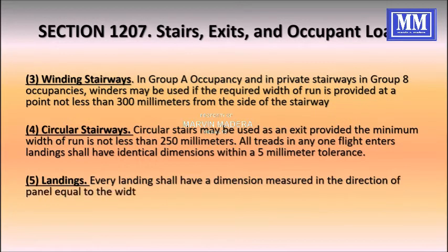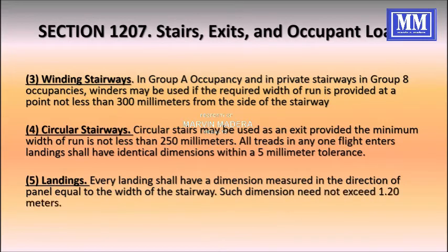Landing. Every landing shall have a dimension measured in the direction of travel equal to the width of the stairway. Such dimension need not exceed 1.2 meters.